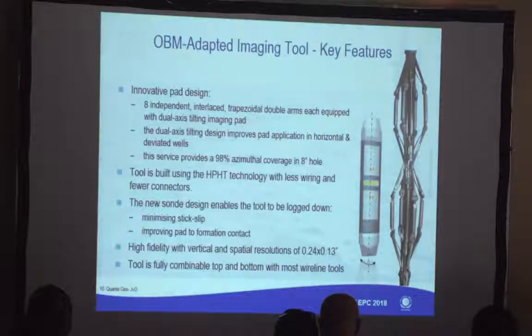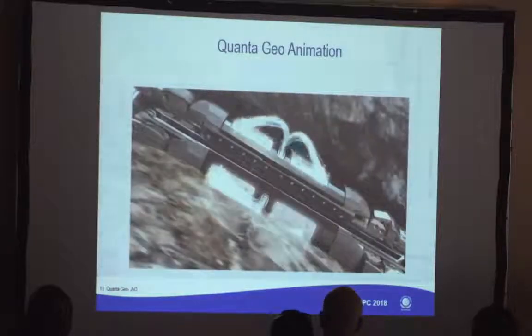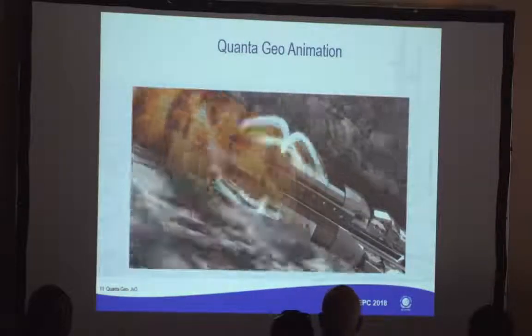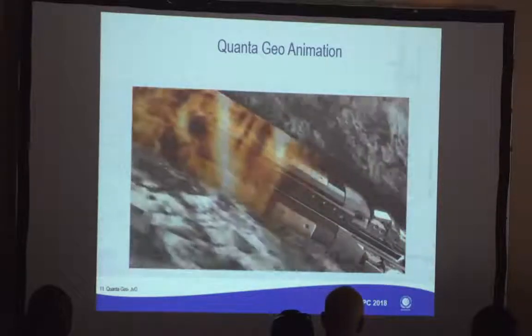This is the tool that we use to make these measurements. So again, it is a tool with pads, just like all the other dip meters and electrical images. We'll always look at a type of sonde with scanning pads that seek to have good formation contact. They're all built around that principle. And I just tested my animation so it should work. So this is what happens. In this case, you see we're running in, we're logging downwards.